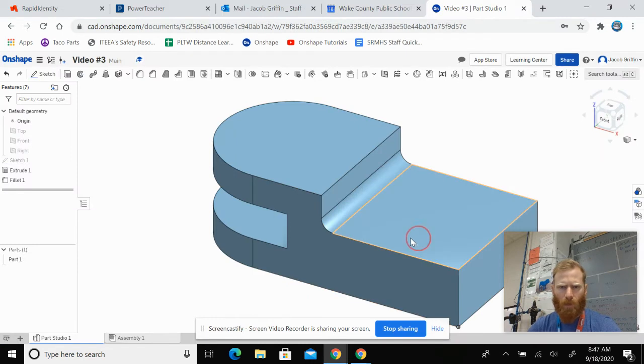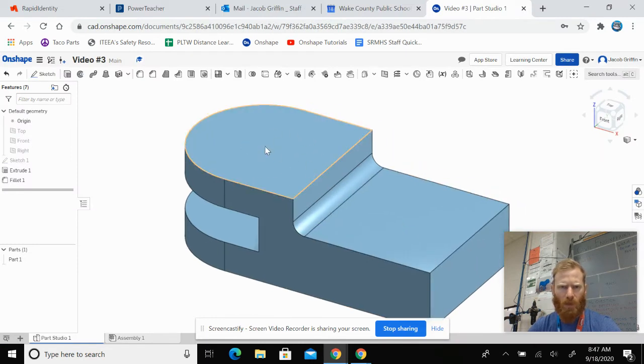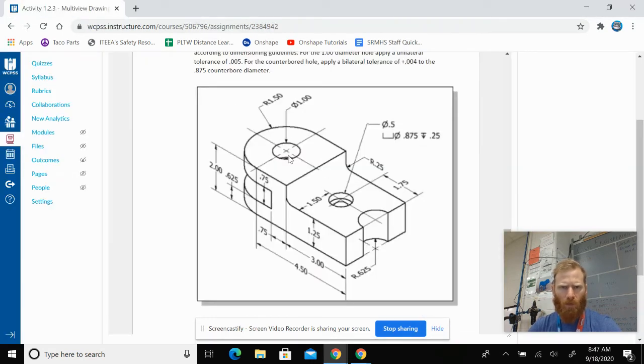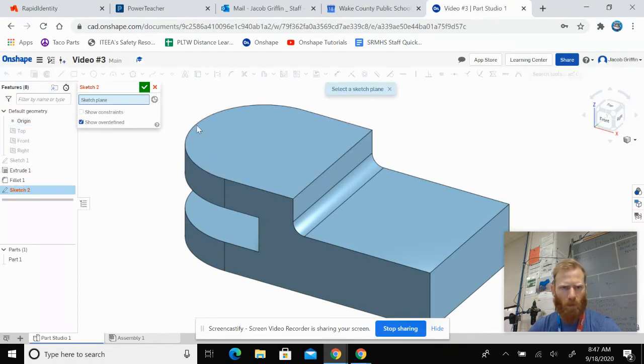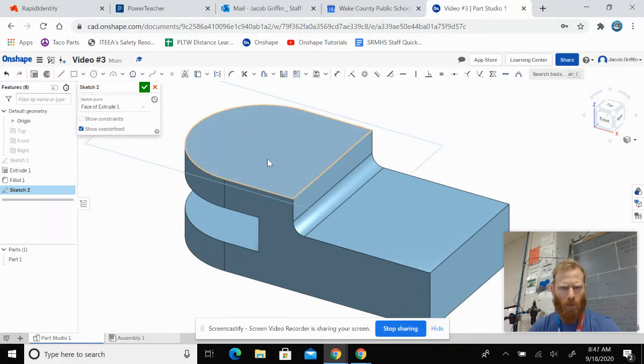All right, let's start with this upper face, elevated section, and draw this 1-inch diameter hole down through it. So that's going to be pretty easy. I can go into sketch mode, and I'll show you how to use the hole tool on this one. All right, so I'm in sketch mode. I want to draw on top of this piece. I'm not even going to change it to look down on it, because all I'm going to do is go up here to my point tool, and I'm just going to plant a point.